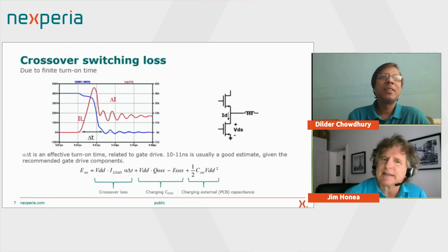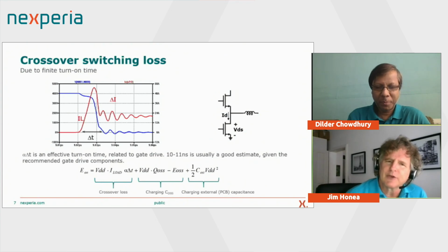Yes, that's accurate. You'll see specifications put on loss during zero voltage switching, like hysteresis loss, where you have a non-uniform charge and discharge cycle, and with superjunction MOSFETs in particular, people have discovered that you will create loss going through that charge-discharge cycle, even though externally it looks like you're achieving zero voltage switching. The GaN FETs won't operate in that same manner.